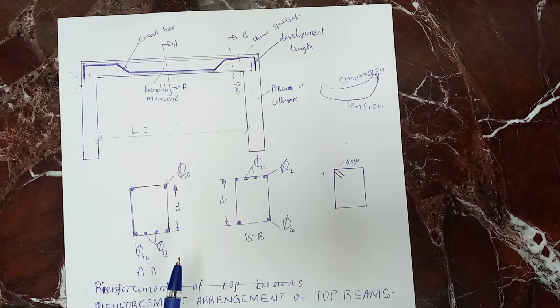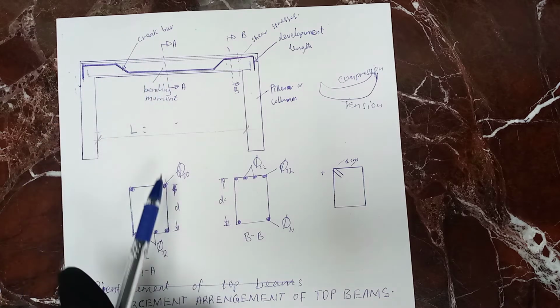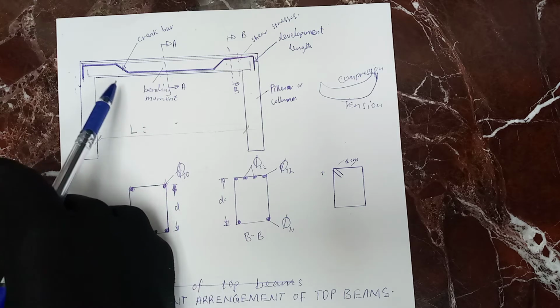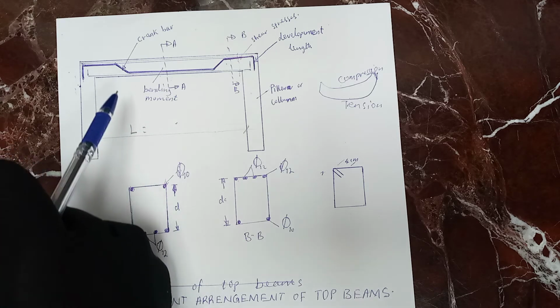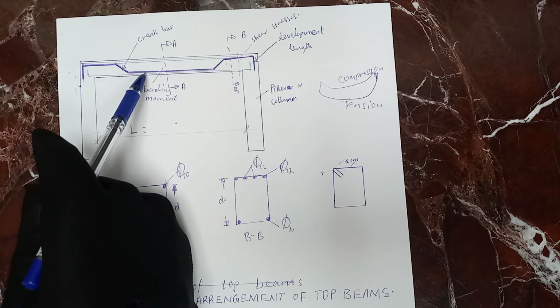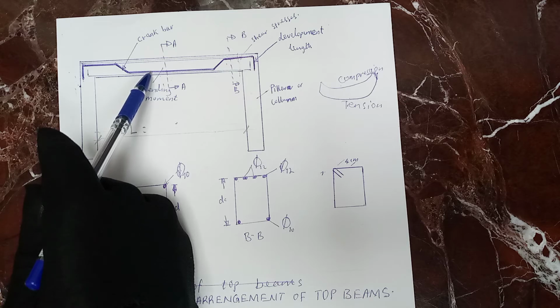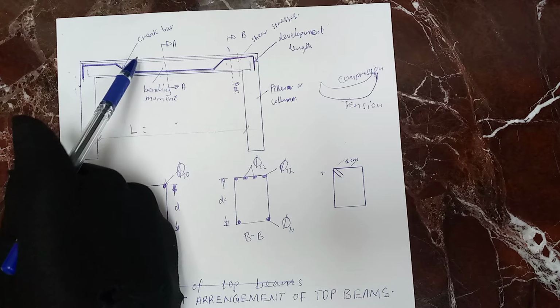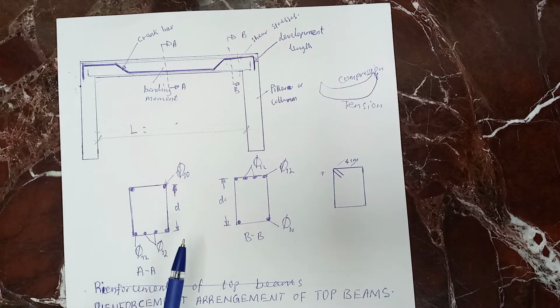12, 12 is down, because down it is always weak. Concrete is always weak in tension and strong in compression. That's why we always advise to use a maximum of steel rod where there will be tension, and use a minimum where it will be compression.